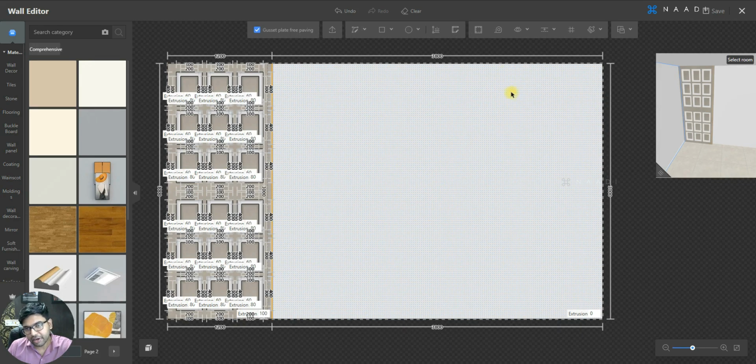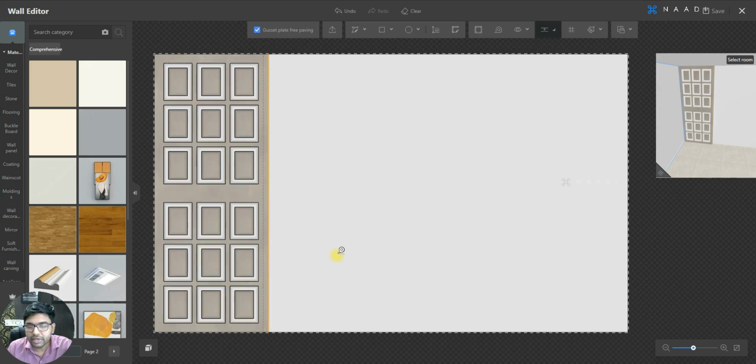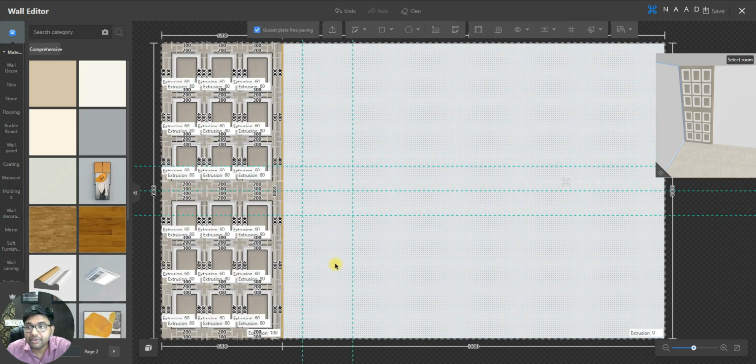And once it has reached the right hand side part, I'm planning to naturally transition it into a normal extrusion based wall panel. So for that, first you could use the reference line, shortcut is T, to demarcate the region for your surface to build. And once this is done, now we could precisely start with dividing the surface.